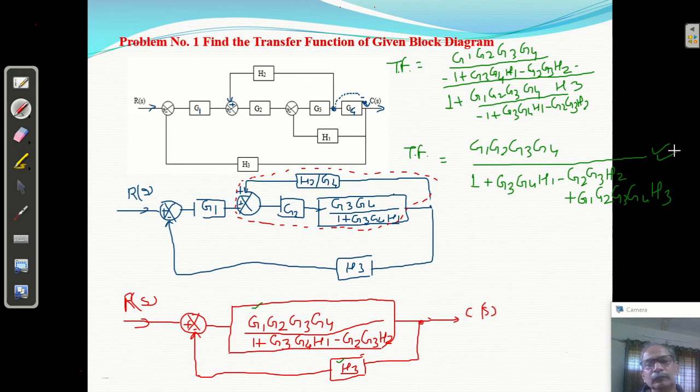First of all, you have to simplify the given block diagram, and you can see here the first step was this block, this is the takeoff point, we have to shift here. Clear? So I told you already, if in the first step the gain here is K, for example, then here its value becomes K into G4. If you are shifting here, first divide by G4, so here H2 upon G4 into K into G4 gives you gain K. So the gain should not be changed. Okay, so that is the way. Anyway, that is a step I have explained.